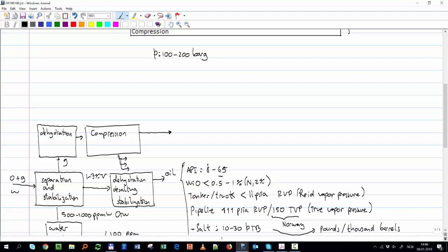Okay, here comes something interesting. Water dew point, okay, is minus 18 degrees Celsius, okay, at 69 bar G. It means that to start getting water out of this gas, I have to go down to minus 18 degrees, exactly at 69 bar. It's a strange number, I know, but we are going to go later to the phase envelope, and you're going to see what that means, okay?